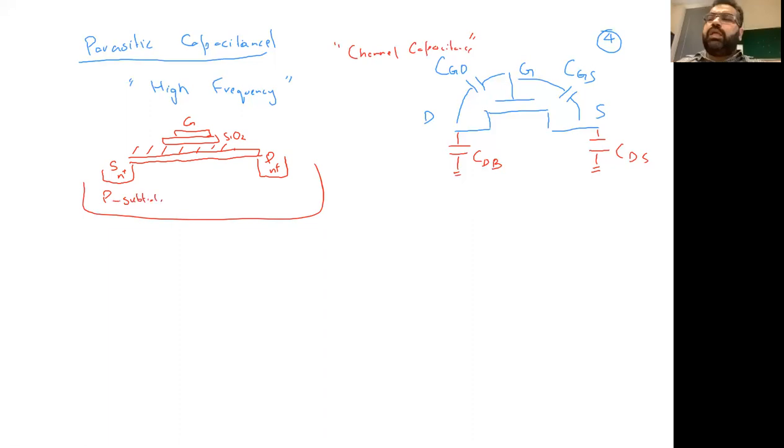So we will see that. Let me draw exactly the same; it doesn't matter because they are interchangeable. This is your drain, N plus highly doped, and this is the source, N plus. Between the gate, this is a conductor, the gate, and there's an insulator, and after that there's again a conductor. So it's going to be a capacitance, commonly known as CGS.